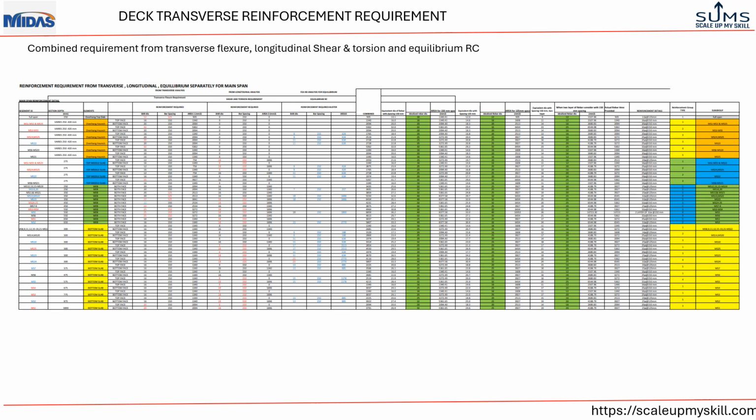This is the total requirement determined in the transverse direction of the deck, which is a combination of transverse flexure, longitudinal and shear torsion requirement, and anchorage and equilibrium reinforcement requirement at different segments. So based on this finding, the detailed design of the deck is performed.